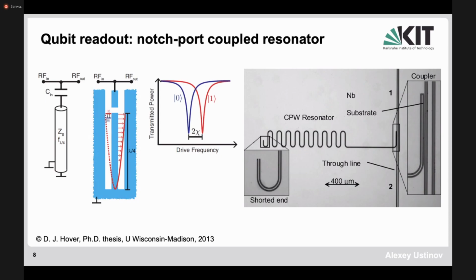So it's actually an antinode of the AC magnetic field. The fundamental mode corresponds to a wavelength which is 4 times larger than the length of the resonator. So it's a so-called lambda by 4 resonator, which of course also leaves enough space to couple the transmon qubit at the open end here, and the flux qubit, if you want, you could couple in the maximum of the electric field.